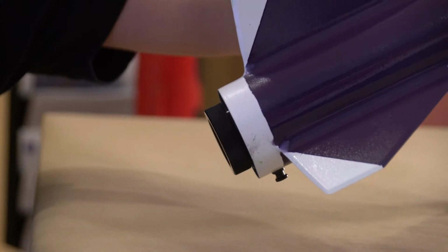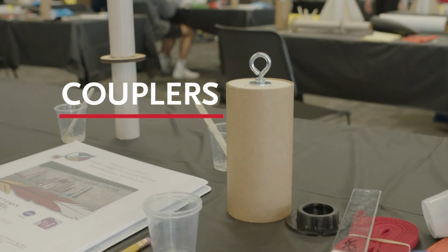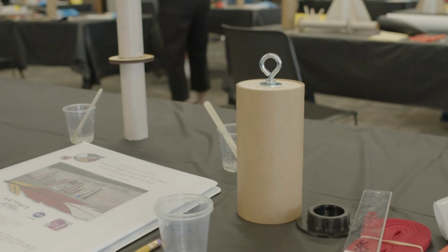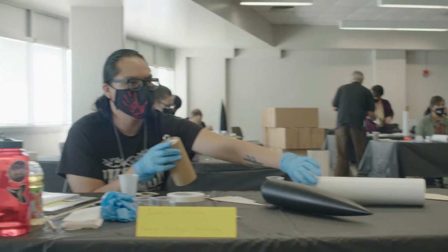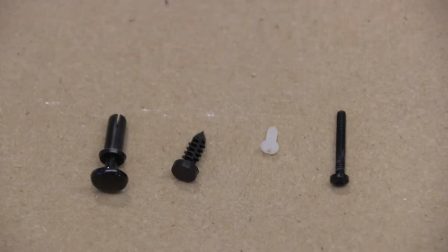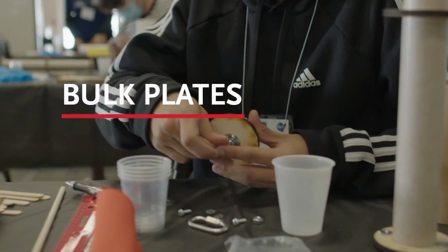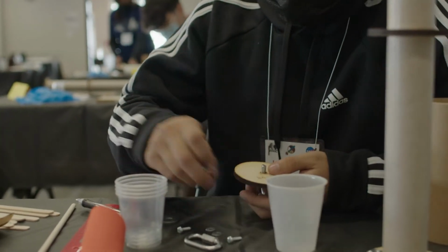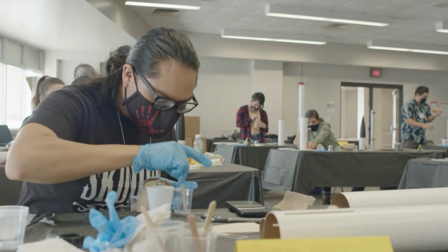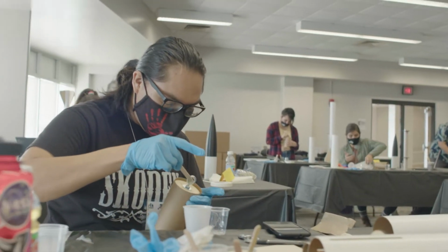A coupler is a tube whose outer diameter is equal to the inner diameter of the airframe, so that it fits snugly inside to connect multiple segments of the airframe. While these are initially just pressure fitted, make sure to test and use shear pins for launch. Bulk plates are circular discs that fit inside of tubes to separate segments. Remember that when deployment charges ignite, the bulk plates take the direct force, so they need to be well bonded.